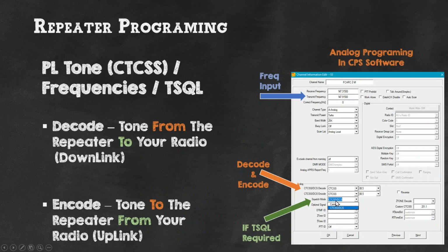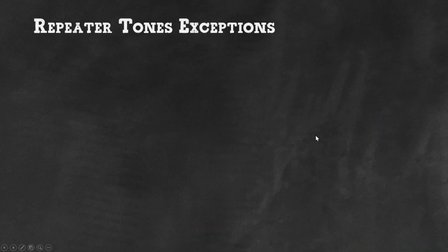This is how you would typically program an analog repeater within CPS. You mark analog, you can put turbo because it's typically further. Turbo means the greatest power that you want to put it at. 25K is a wider band, analog local, and off you go. Analog local is basically for my scan list, which is another video. You can see this can get very complicated very quickly.